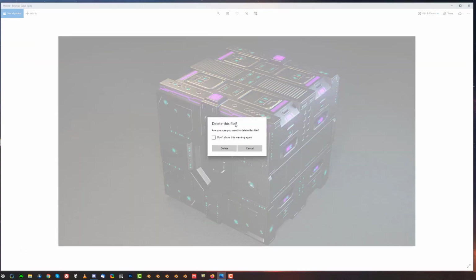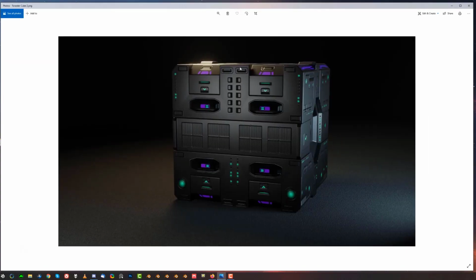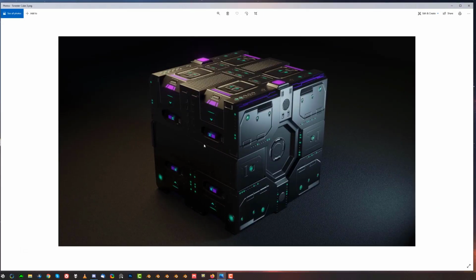So I'm gonna pick the, see again here, issues, and that's a lack of weighted normals because it's a flat surface, right? So there's no way you should be getting any pulls even if the geometry was bad. So the reason here that you got these lines, you need to start applying weighted normals to your object, okay? So weighted normals modifier, which is, by the way, alt click on sharpen in Hard Ops. So I'm gonna probably go with this one, and you cannot see these distortions here as well, so they're on this side, right? So that's the one I'm gonna go with, okay?